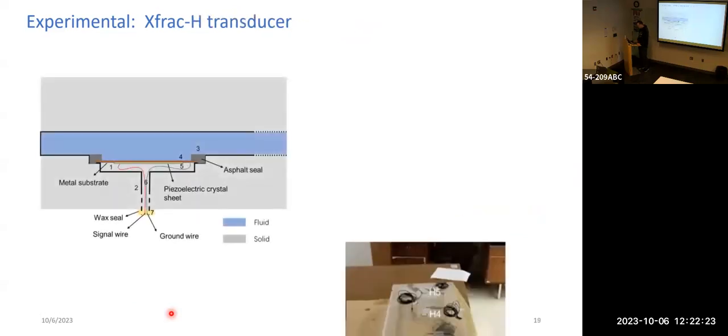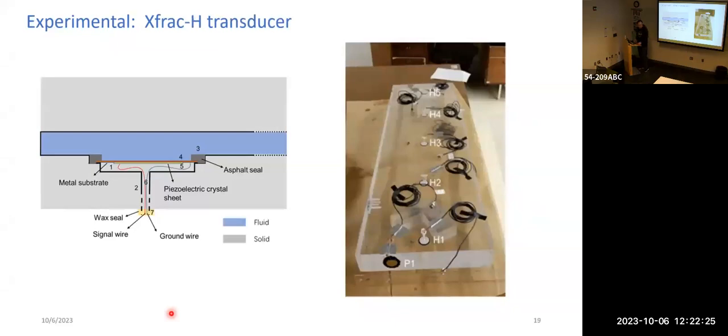And that is the design of the transducers. The design is contributed by my collaborator, Nikolai Dior, and he designed this airbag piezoelectric sensor, which uses the flexural mode of the PZT film, which can have higher sensitivity than the compression mode of the PZT.